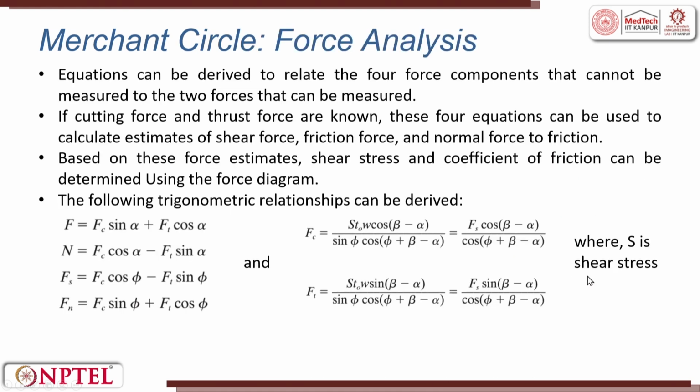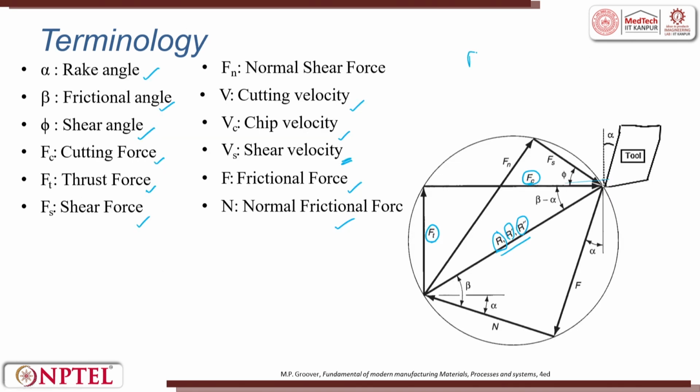Now, let us try to do the force analysis. Equations can be derived to relate the 4 force components that cannot be measured to the 2 forces that can be measured. What cannot be measured are Fn, Fs, N, and F. What I can measure is only Fc and Ft. Now, I have to connect these with respect to this.